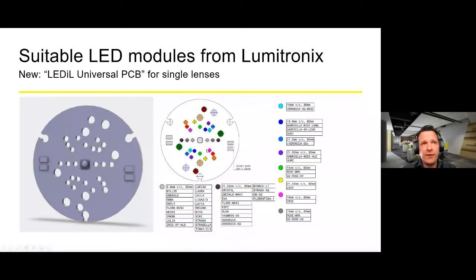So you can easily test the optic before you create your own PCB, for example. That is quite useful and recommended when you are not sure which kind of optics you would like to use. Take this board and use the different color codes to identify which lens fits into this area, and then you can easily use and test it.